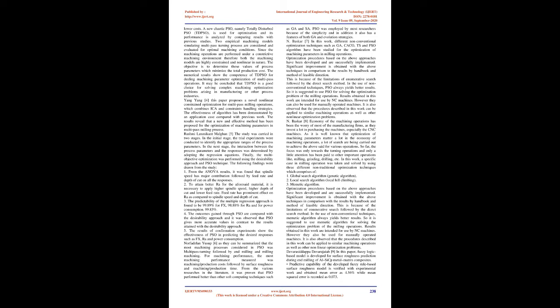2. To attain better RA for the aforesaid material, it is necessary to apply higher spindle speed, higher depth of cut and lower feed rate. Feed rate has prominent effect on RA as compared to spindle speed and depth of cut. 3. The predictability of the multiple regression approach is found to be 99.89% for FX, 98.88% for RA and 99.83% for power consumption. 4. The outcomes gained through PSO are compared with the desirability approach and it was observed that PSO gives more accurate values in contrast to the results attained with the desirability approach. 5. The results of confirmation experiments show the effectiveness of PSO in predicting the desired responses such as FX, RA,